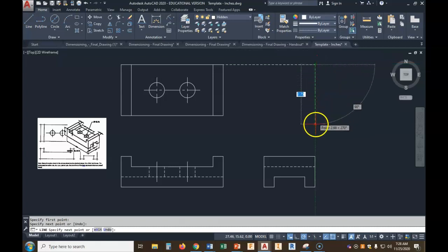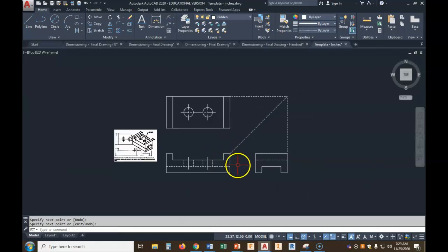Now, I'm just doing this for reference to show you that these line up. Because remember, when we take this front end and rotate to the right, then this is our right view. This is the back of the object. When I rotate around to see the top, this is the back of the object. So see, back, back, it lines up. Look like this, top, top, it lines up. So, this is the point that we need to draw the 45 from. If it's done correctly, it would hit at the top corner of the front view, if it was a solid piece. So there we go.